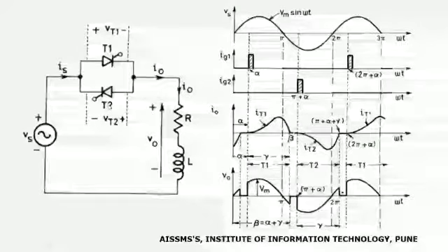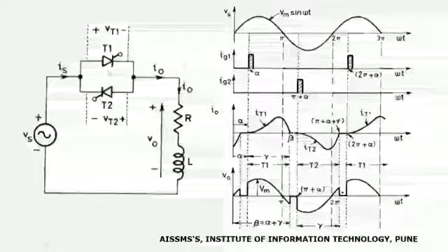So we can say that T2 is operating like an open switch. Now, though thyristor T1 is operating in forward bias condition, in the initial time period no triggering pulse is applied to T1, and hence T1 is also operating like an open switch, and hence there will be no connection between the source and the load.